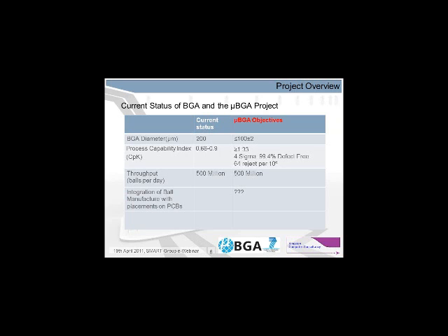We're aiming at a CPK of 1.33, which relates to 4 sigma deviations around the average, so that almost all balls fall within 4 sigma deviations of the tolerance, which means 99.4% of the solder balls are produced defect-free, which in terms of a rejection rate equates to 64 in every million.